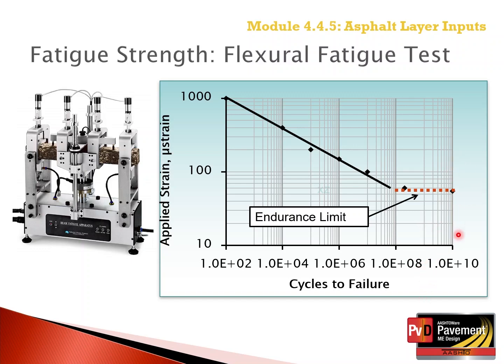And as shown here, the endurance limit for this one temperature and set of mixtures would be about 58 mils per inch or microstrains for this temperature and mix.